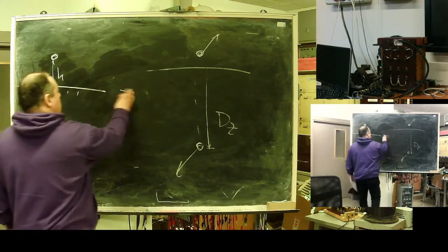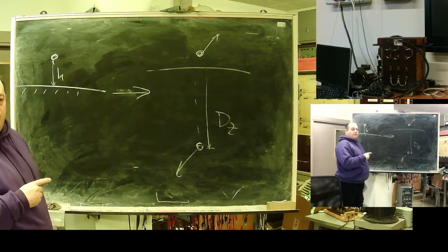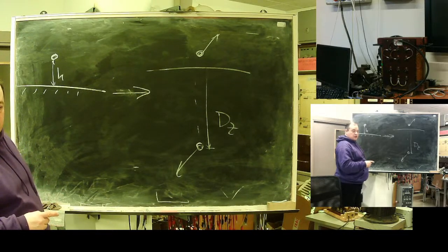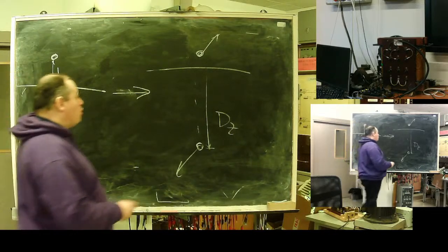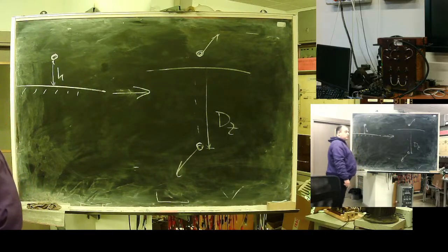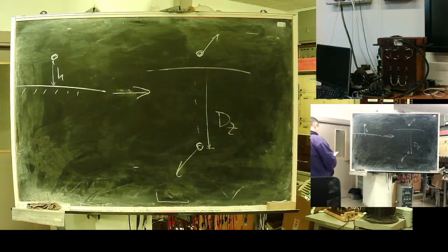Carson's idea was to use a two-wire model with the same current density distribution. Why? Because Carson knew the solution for a two-wire system. The idea was to find a two-wire system with a similar current density distribution, and for this system Carson already knew the solution for the line parameters.